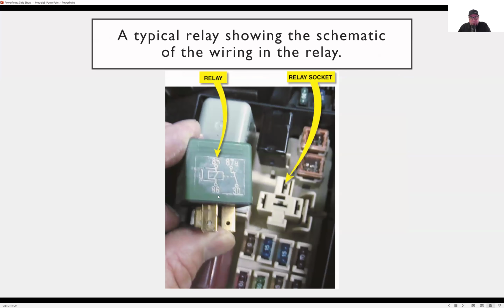The relays themselves sometimes do have numbers on them, which helps you identify them, and sometimes they don't. If not, we learn how to measure them using a meter to identify what a few of the numbers are and where they are. Relays are usually located with the fuse box. When you pop off the cover of the fuse box, you'll see fuses and you'll also see relays. Relays are about the size of a quarter in physical dimensions, but they're thicker. Sometimes they look like a little mini charging brick. They're not big components, they're small components.